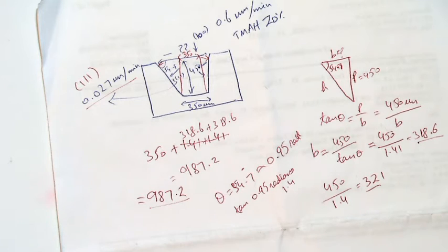Now we have our mask, we design it, we print it in the photolithography, and now it's on our silicon dioxide, and now we have to put it in an etchant, which is TMAH in this case, to make this structure, right? So should we leave it there forever, or should we do etching for some time? How do we calculate how long we have to do etching in order to achieve this kind of structure? Can you calculate how long we have to do etching?